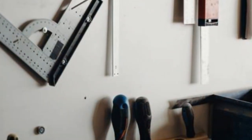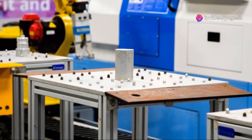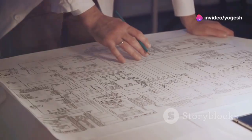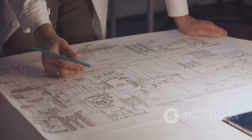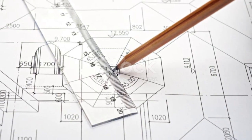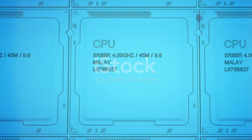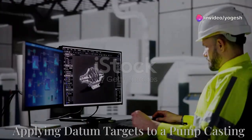Properly indicated datum targets eliminate ambiguity and ensure repeatable setups. Remember, clarity in your drawing is key to manufacturing success. Use basic dimensions for all target locations. With these steps, your design intent is unmistakable.